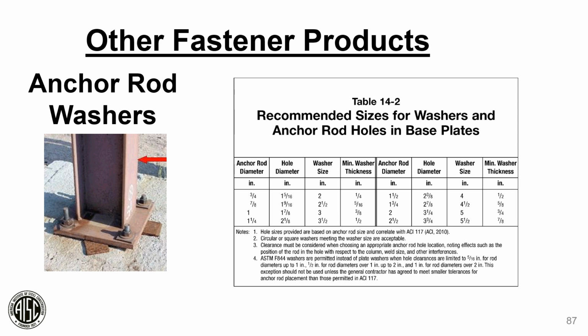Now, the washer size is sized sufficiently to cover the hole, and also a proper thickness so you will not have a problem developing the strength that is required. So keep that in mind. Also keep in mind, a washer doesn't need to be round. It can be square. Either one will work.